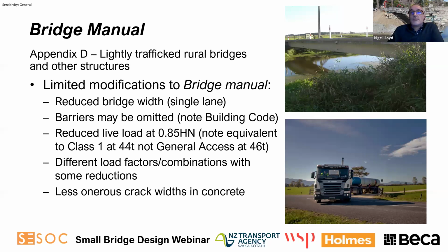Appendix D gives you some different load factors and combinations, less conservative, lower risk, and therefore there's some benefit there for smaller bridges, some less onerous crack widths in concrete, and that's about it. But it's worth noting that there are other factors in the bridge manual that deal with the reduced scope that you have of a smaller bridge.